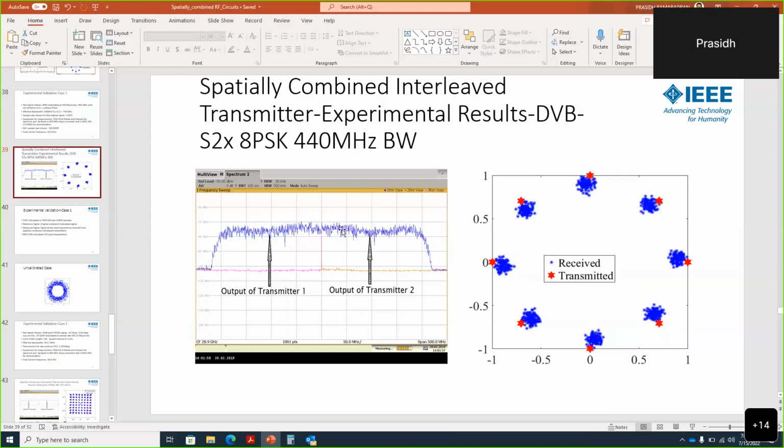Say, for example, if we try to generate a single carrier wideband modulated signal, one of the ways to identify such differences would be to take the first difference, or essentially the first derivative of phases around the intersection area. Any such skew, or any such discontinuity of one relative to the other, is going to manifest in the form of a spike there. So then all that one has to do is correct the phase of the second relative to that of the first.